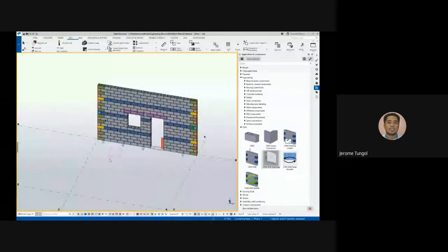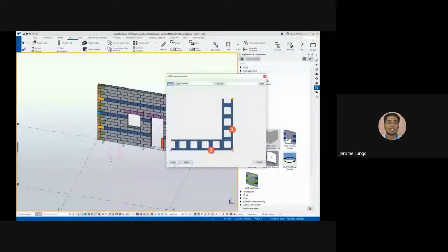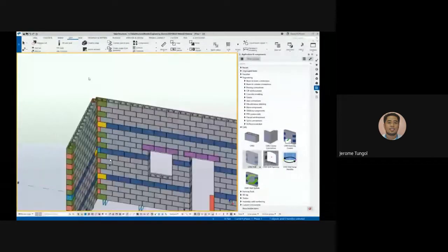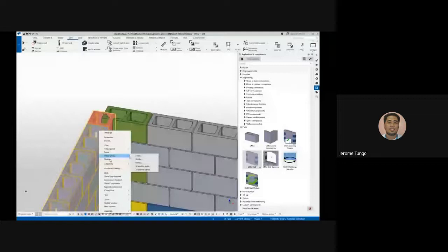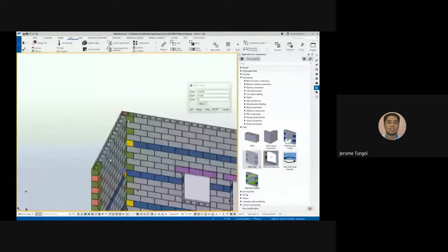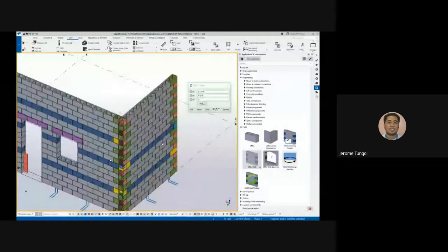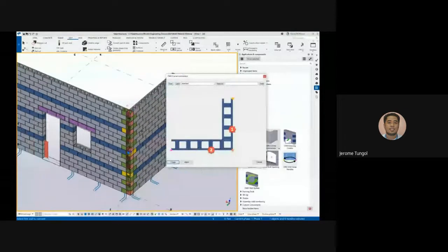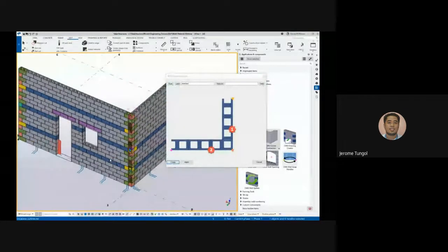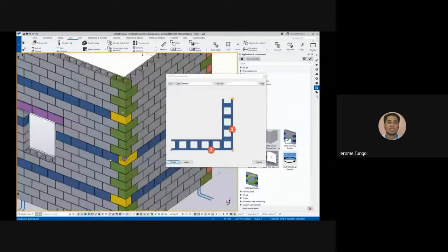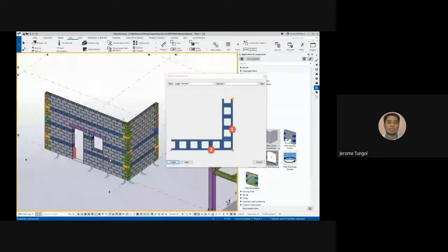And then also, if you lay out corner to corner masonry, just like this, and you just only move it, as you can see there are clashes on the CMU walls, those faded areas, meaning they are not cut. So we have a connection, the so-called CMU corner connection, so that you can model it correctly. As you can see, it trims all the CMU walls that intersect.